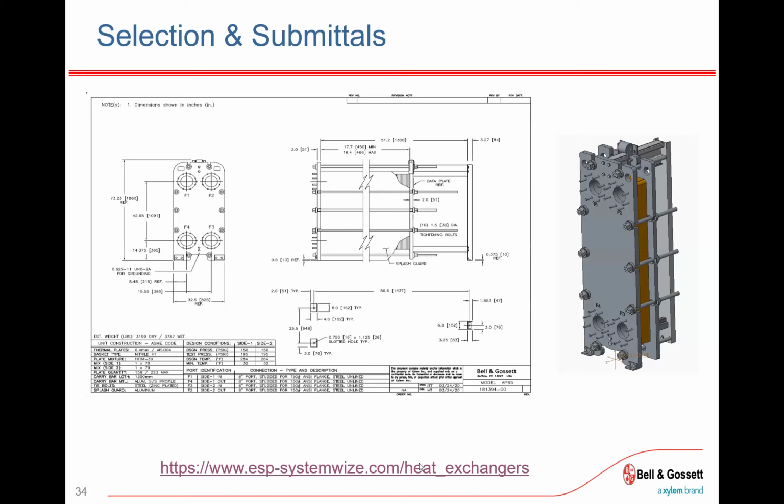So, oh yeah, it just says here, the stainless steel wet parts requires the nitrile gaskets. And obviously this may result in a higher, it's definitely going to result in a higher price because you're using stainless steel in your connectors rather than just steel, right? So it's clearly going to be at a higher cost. Just about any type of system that you see that's potable rated versus the non-potable version, the potable version is always going to be a higher cost.